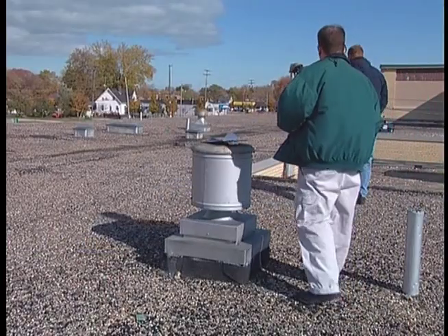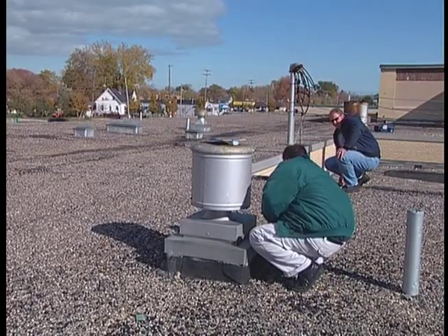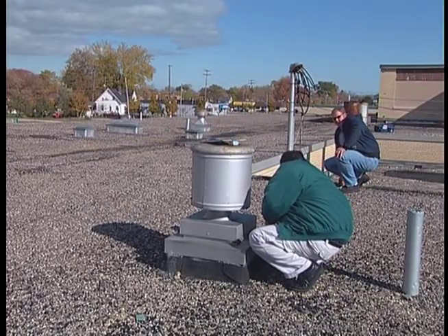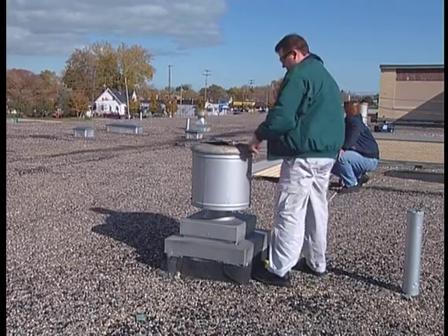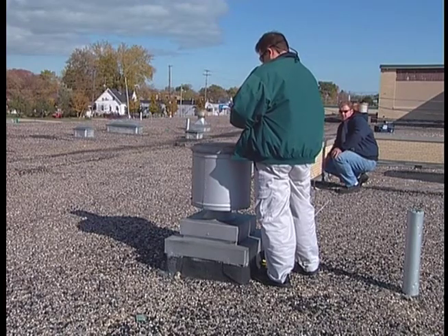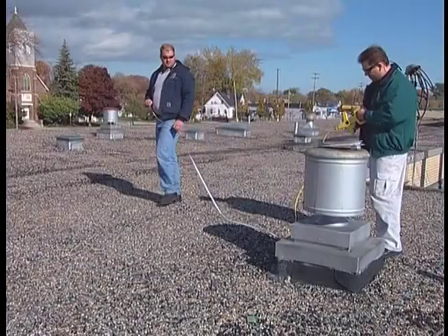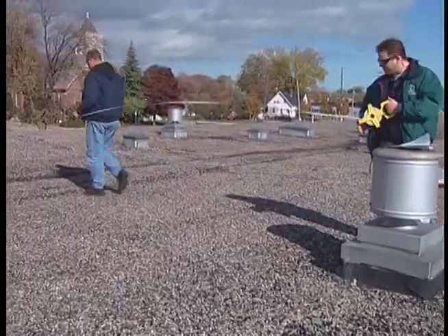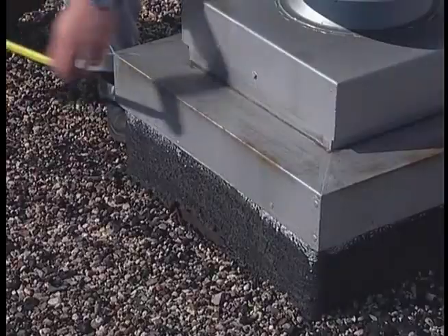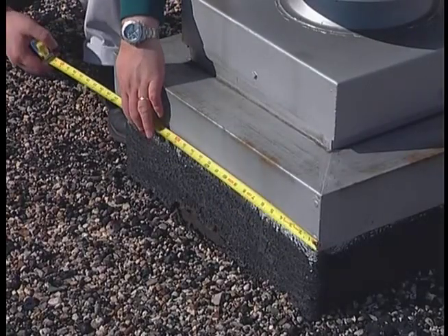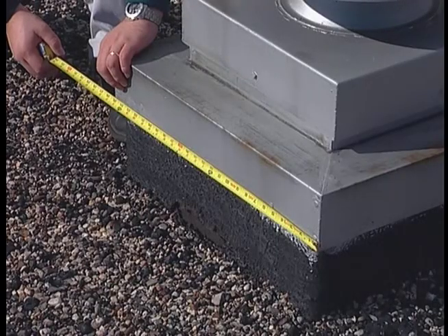Here's an important point about HVAC units, mechanical equipment housings, or similar large rooftop penetrations. Accurately measure all large penetrations that you will have to work around. Locate them accurately in your sketch by measuring from two perpendicular walls. This will allow you to custom design a deck sheet that will work around that penetration. Also, get the measurements of all the rooftop curbs on which the HVAC or other rooftop mechanical equipment sit.